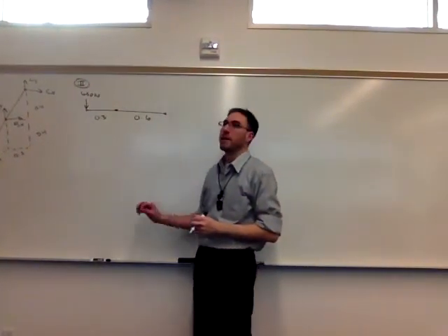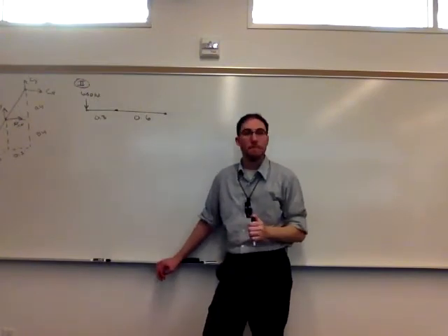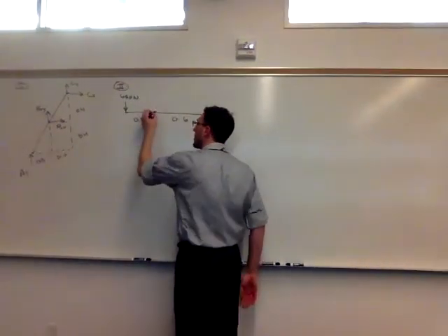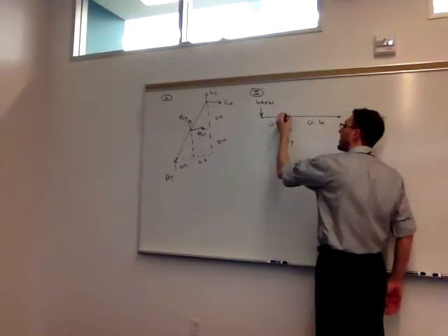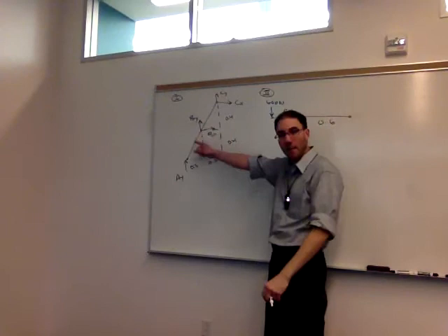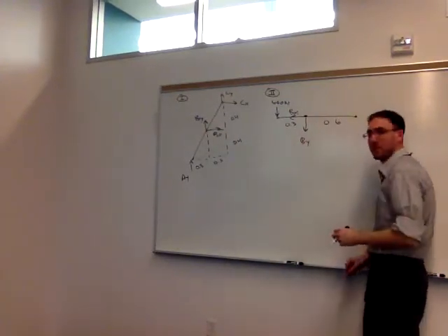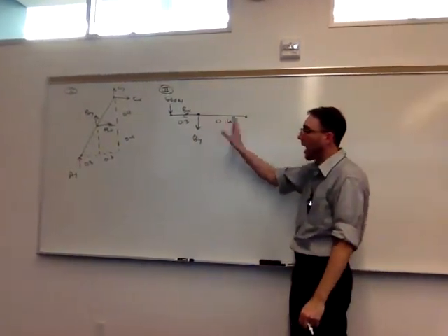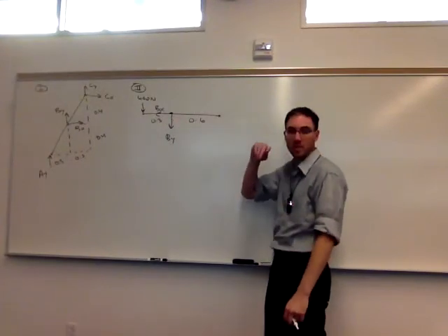And then what else is affecting member BD? BX and BY in the opposite direction. Right, so I already made the assumption of direction, so I'm obligated in this picture to draw it equal and opposite directions. So that choice, I already made the choice up front, so this has to be this way.